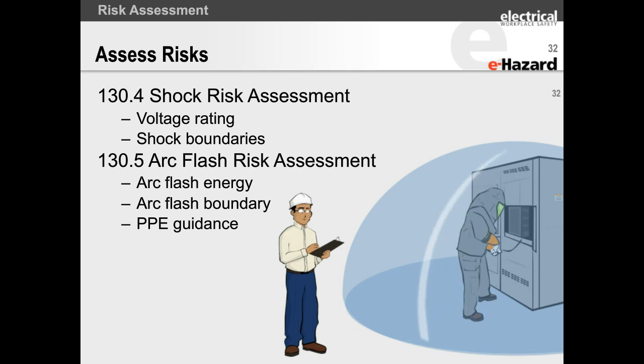Arc flash and shock is important. One of the things that I think gets kind of lost in this, we got a lot of publicity for arc flash, and that's great, but most people die from shock. And most people get an arc flash when they get a shock. And if you prevented the shock in the first place, some of the arc flashes would go away.